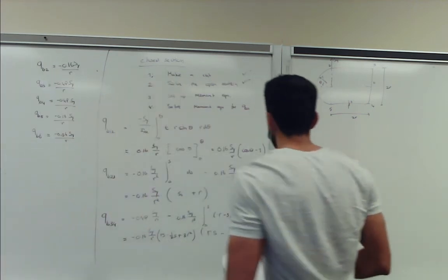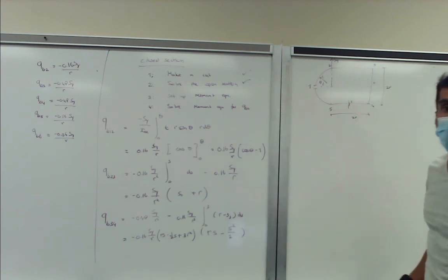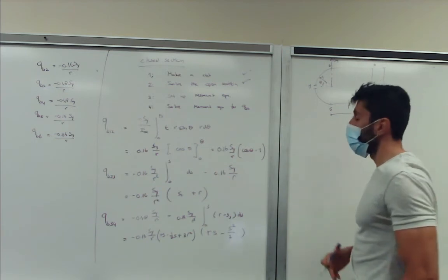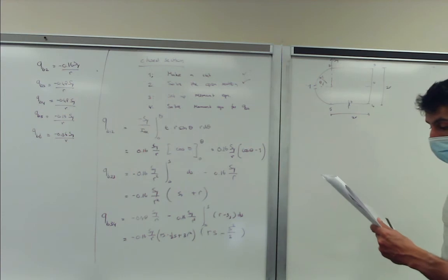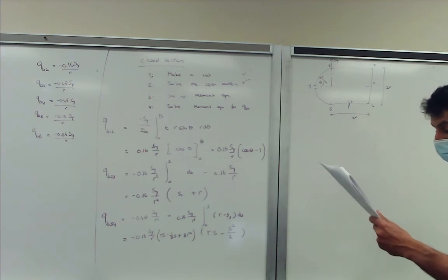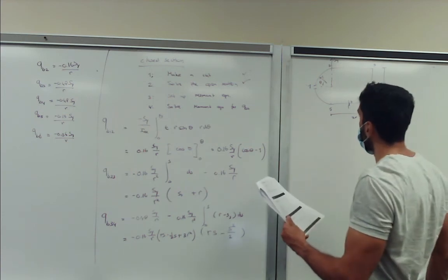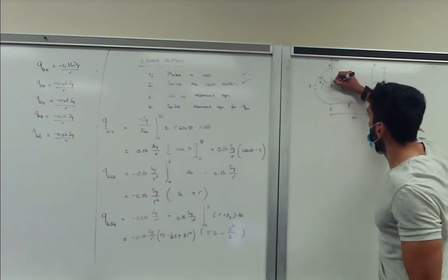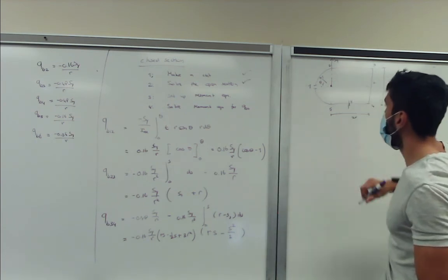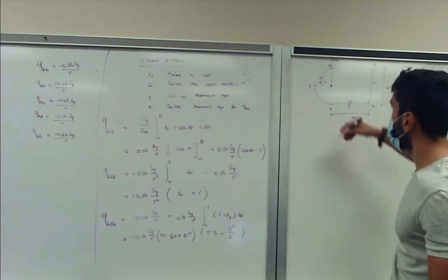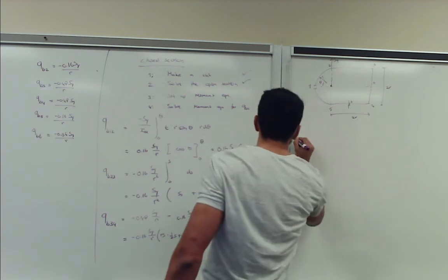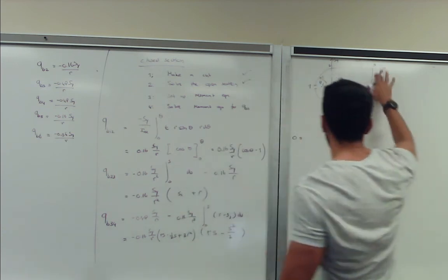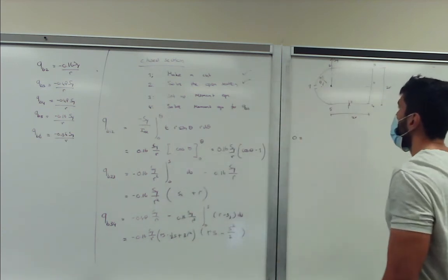So now what we do is we set up the equation and we calculate the correction shear flow. So we set up the moment equation. We want to make things easy for ourselves. So the location that we pick for the moment equation, in this case, will be this location here where the origin of our axis system is. So SY doesn't have any moment arm, so that part is 0. And then we look at the shear flows and what moments they cause.